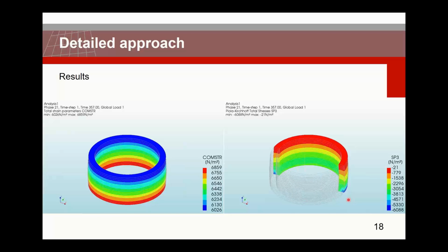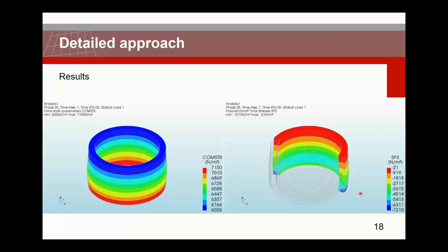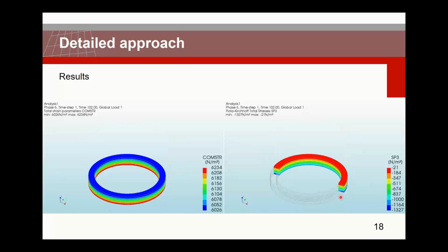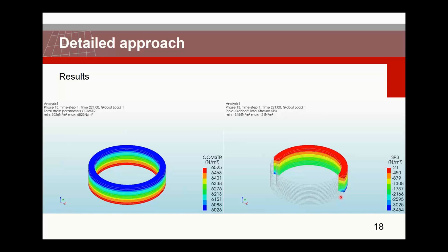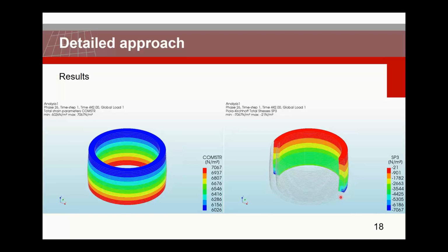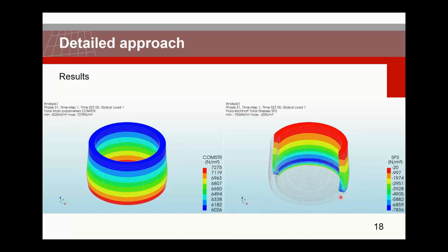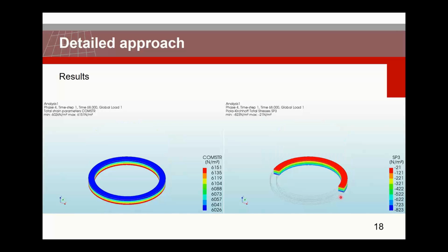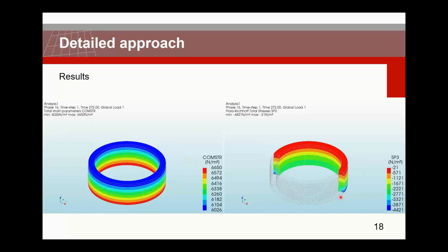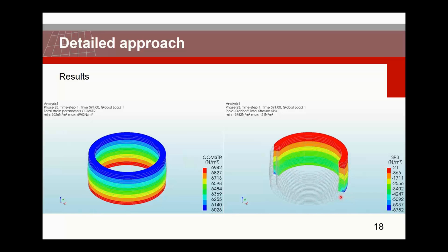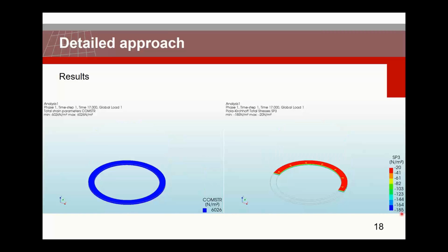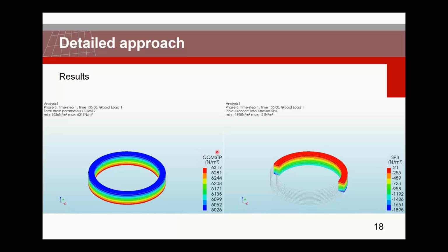And from some moment, we can see that the compressive stress in the bottom becomes equal to the compressive strength. And then we see plastic strains, and in the end we see instability due to plastic failure together with buckling. So it's actually a combined failure mechanism in this case. If you look closely, you can see that the compressive stress becomes larger than the compressive strength.